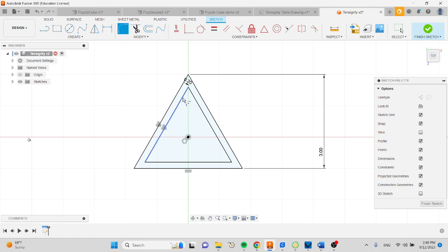So I'm going to click 1 line and then the second line. And you're going to notice that's way too big because it's defaulting to 0.7. I don't want 0.7, I want 0.1. So type it in. And as long as you keep that in there, you can just click on the next 2 and the final 2. And it'll change all of those to 0.1. Press Enter.